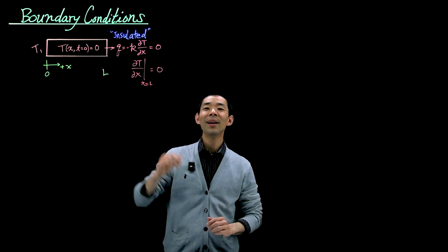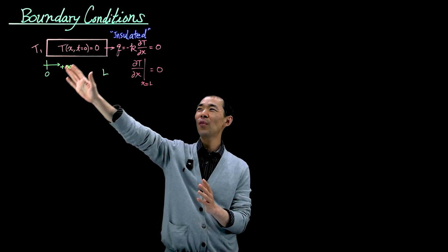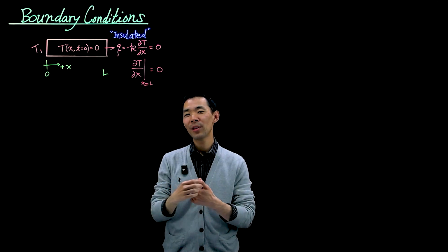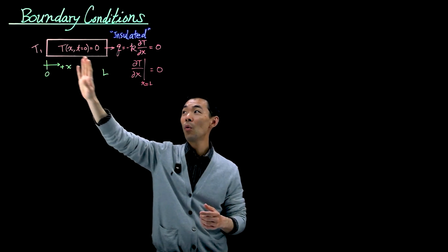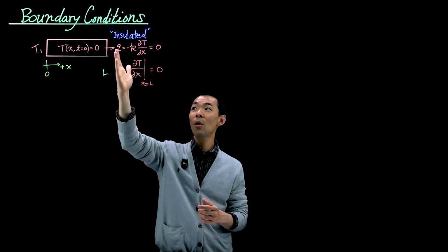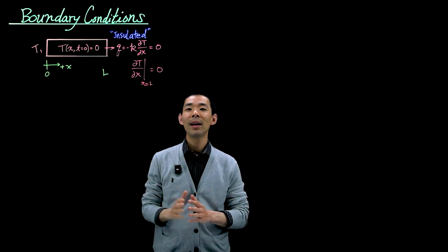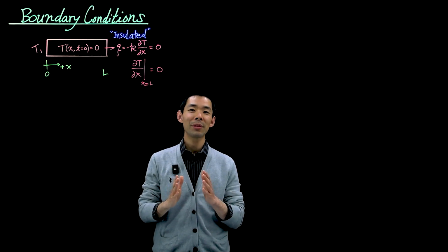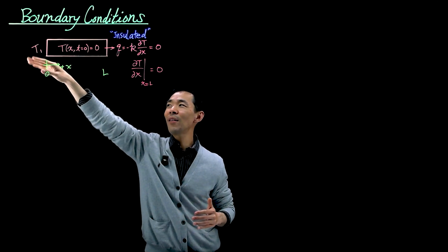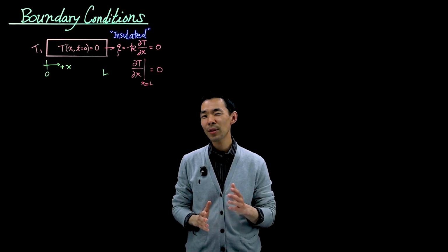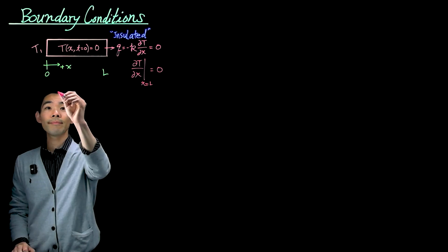Just like that. So our goal, as usual, is to solve for the temperature profile inside this material as a function of position x and time, subject to these two different boundary conditions: one on the left set to a particular temperature, one on the right set to no heat flux leaving that surface, and with the initial condition that at all positions x the temperature is equal to 0. Just like the last lecture, we already know that the non-homogeneous temperature on the left-hand boundary is going to cause a problem. So just like last time, let's split the problem into two parts.